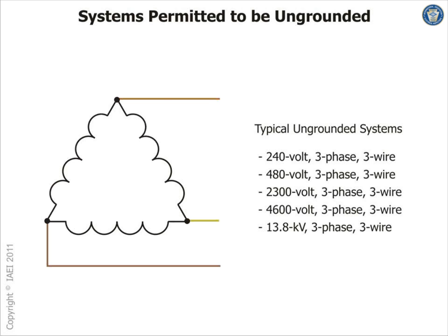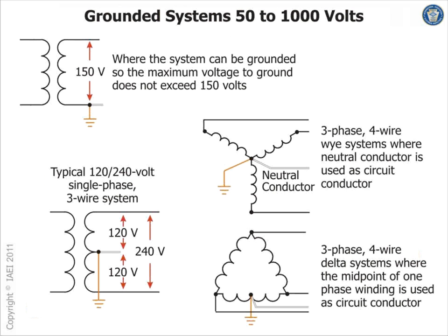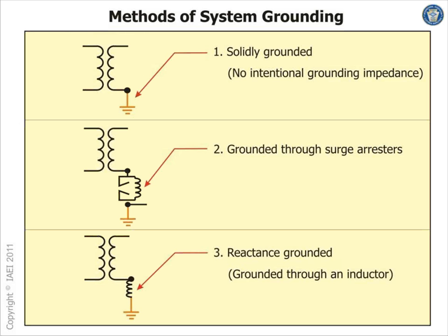So that's, I thought, just to start with first, the difference between the systems that can be grounded. When we say grounded system, we talk about the winding of the transformer being tied to the ground, not the box, not the frames. So these are the 2 systems, the grounded and ungrounded. There's something in between. I'm going to go directly into the system in between. There's also, to take advantage of a grounded system fully, what IEEE 142 calls a solidly grounded system. That's the most common one here. You get 120/277 voltage from it.